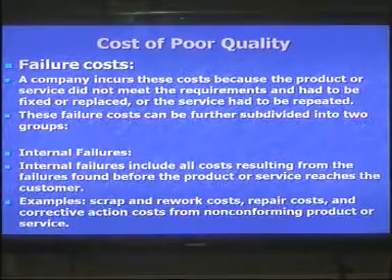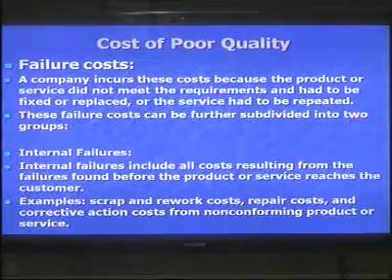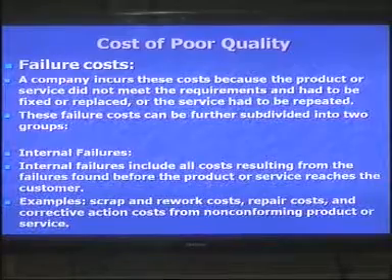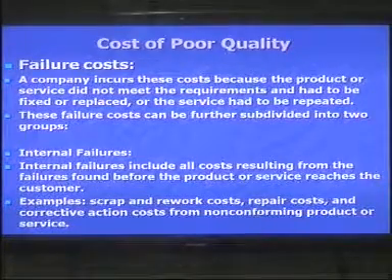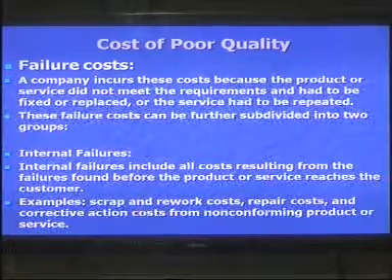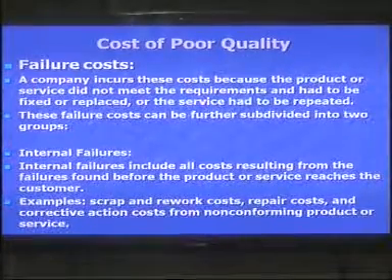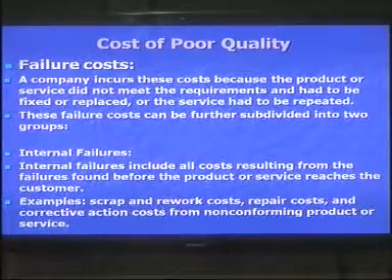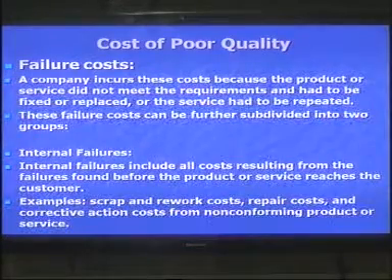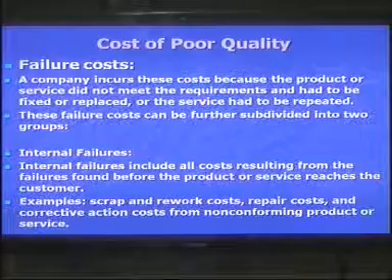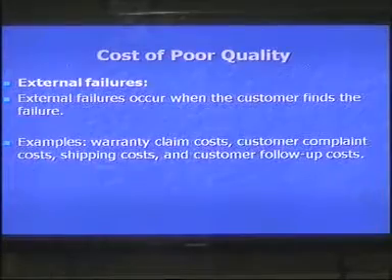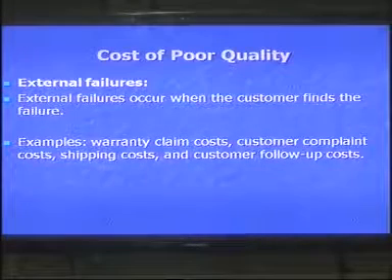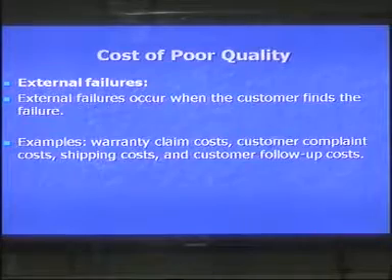Failure costs. A company incurs these costs because the product or service did not meet the requirements and had to be fixed or replaced, or the service had to be repeated. These failure costs can be further subdivided into two groups. Internal failures. Internal failure includes all costs resulting from the failures found before the product or service reaches the customer. For example, scrap and rework costs, repair costs, and corrective action costs from non-conforming products or service. External failure. External failure occurs when the customer finds a failure. Examples are warranty claim costs, customer complaint costs, shipping costs, and customer follow-up costs.